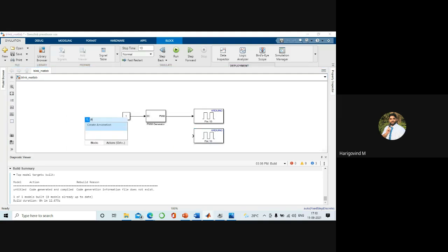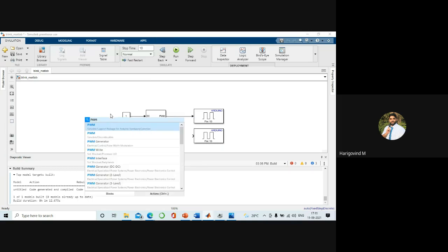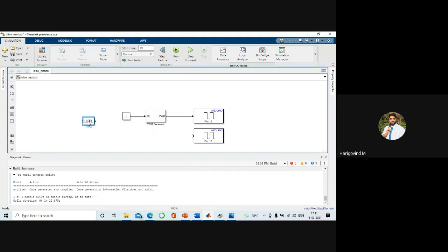What we used to do is use a PWM generator, available both inside the system as well as in the MATLAB library. Just type PWM, meaning pulse width modulation. Both options are almost the same, and give a constant because we need a DC voltage, a specific voltage, right? So that should be constant.